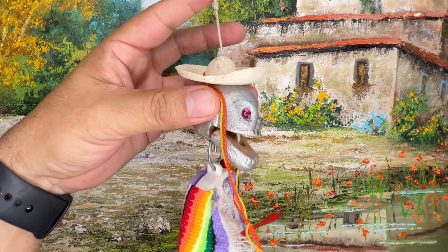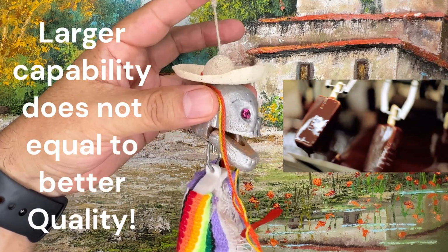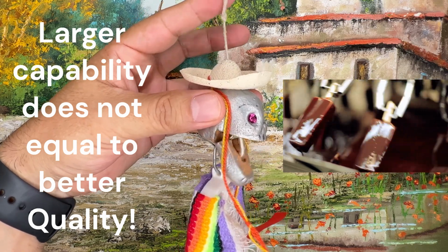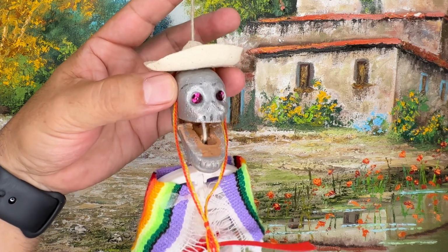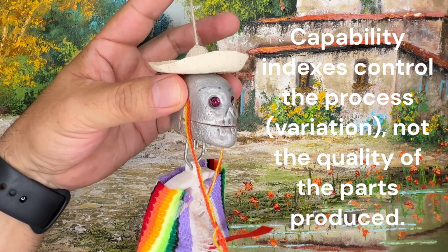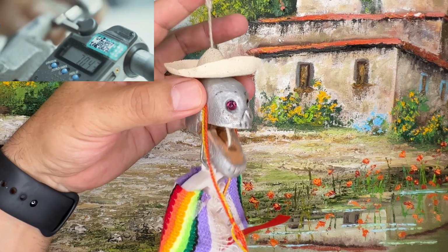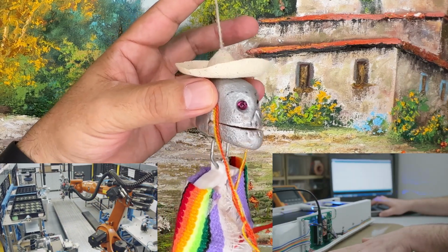But be careful. That doesn't mean, for example, that if your process has a PpK of 1.67, you are making better parts than with a PpK of 1.33. No, no, no. Capability indexes are used to control the process, not the quality of the parts. Quality of your product needs to be controlled via gauges, vision systems, electrical testing, or other devices.